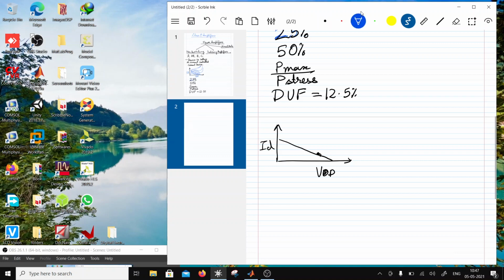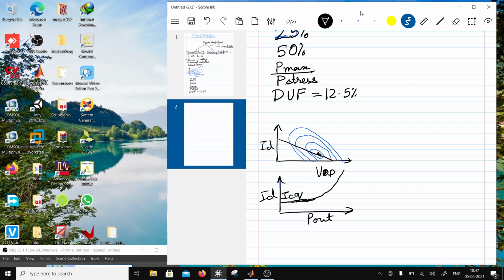So now I swing. To some extent it is going to look like class A, but soon you are going to start clipping this waveform. When you start clipping the waveform, the DC value goes up. So if I was to draw that for class AB, I am going to plot P out. I'm starting with ICQ, the quiescent current, and I have biased it low, and it is going to pick up like this. The clipping causes the DC level to shift, and that changes the DC bias.